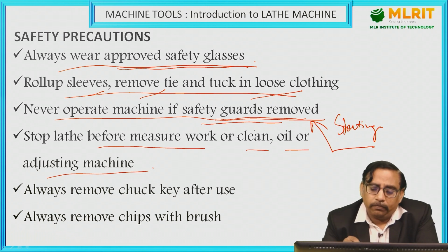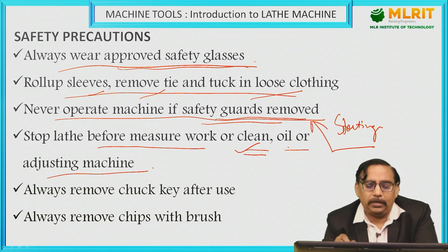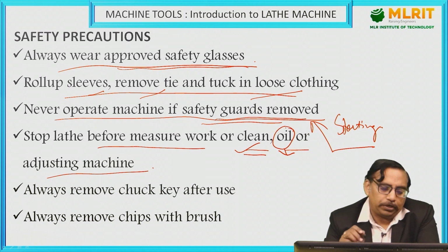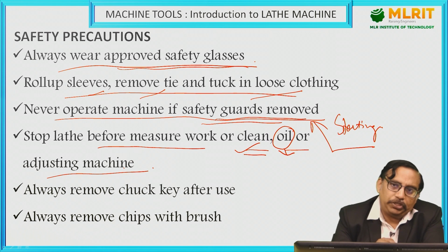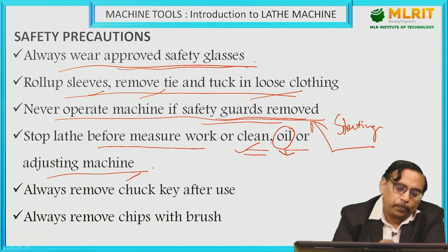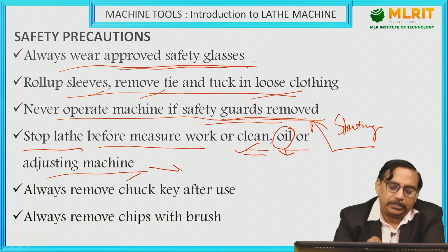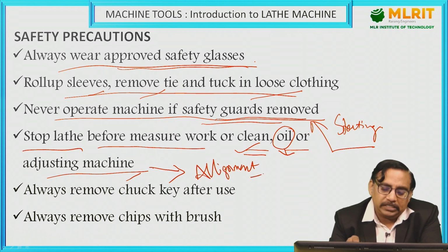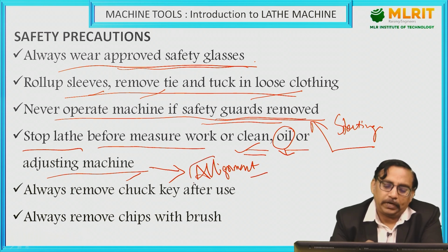And while cleaning the bed also, you are supposed to stop the machine, then do it. For oiling the bedways or any greasing holes, you are supposed to stop the machine, then go for the oiling or greasing. Even for adjusting the machine, you are supposed to stop the lathe, then adjust it. Even for alignment, if alignment has been disturbed in between some operations, you are supposed to stop the machine, then go for alignment.